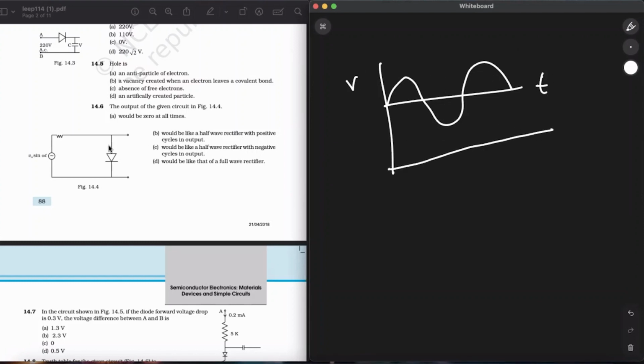What will happen is there's a diode, so it will just allow one part of this voltage to flow like this. Alright. During the half cycle, the diode will be forward biased, so it will let the current flow like this, just like the same concept we did in the previous one. So when the diode is forward biased during the positive half cycle of input AC voltage, the resistance of the PN junction will be low and the current will pass through the circuit. The current passing will be the maximum. So in this situation, the maximum potential difference will be VRMS under root 2. Okay. The maximum potential difference will appear across the resistance connected in series in the circuit. So the result is zero output voltage across the PN junction.